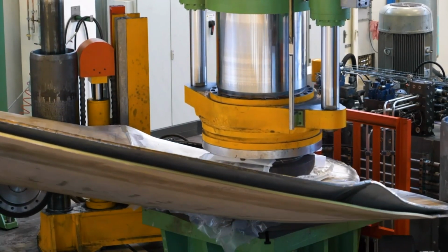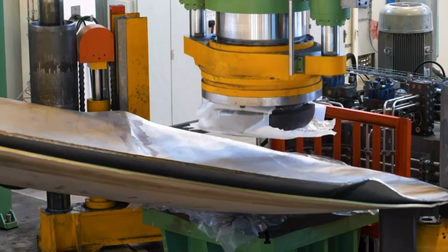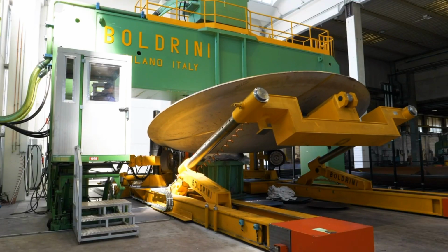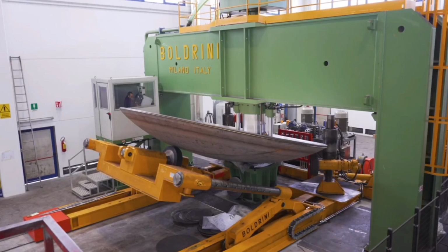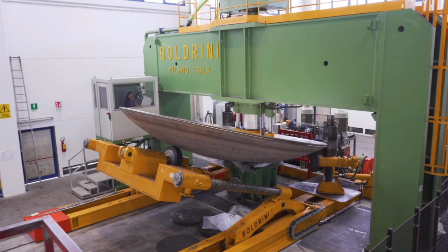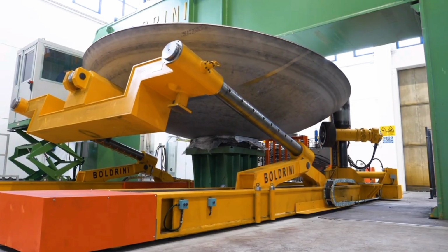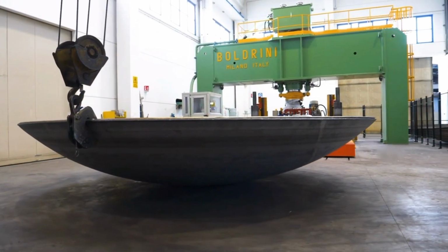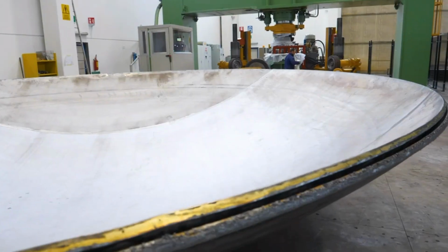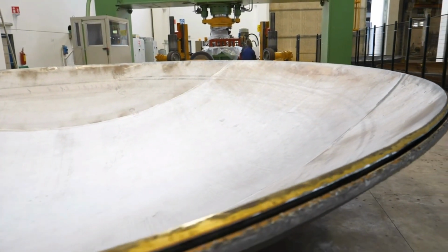Finally, going back to dishing, the formation is only perpendicular to the sheet metal surface, while stretching and thinning are minimal. It is a forming process in which a flat sheet of metal is shaped into a concave or bowl-like structure. It is commonly used to create shallow or deep curved surfaces for both thin or thick and medium size, starting around half-meter diameter to giant spherical tanks. Dishing is used to shaping the individual segment or pieces that will later be welded together to form the complete spherical structure. And this is the method we used several times when I was working at a sheet metal fabrication workshop. We had always sent the segment patterns to our dishing forming supplier.